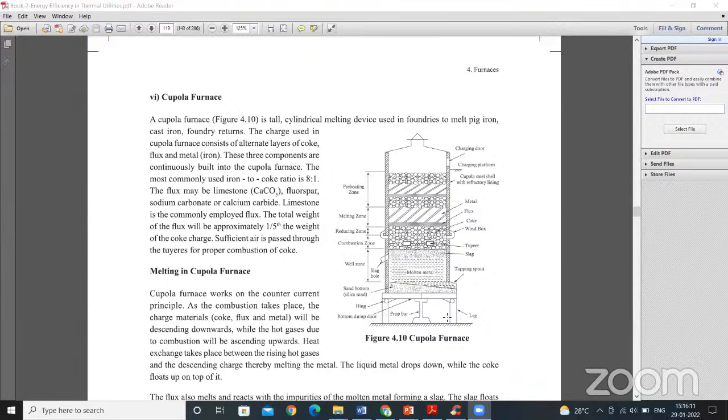Now the advantage of the electrical furnace is that efficiency is higher, and the melting rate is also higher. The time taken to melt one mold of melt is going to be lesser compared to the cupola furnace. Similarly, the cupola furnace requires additional components like pig iron, cast iron, other metals.